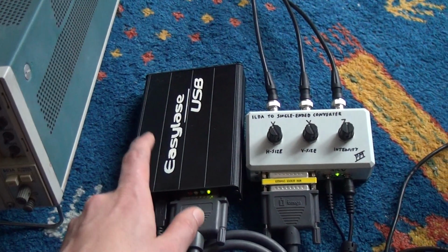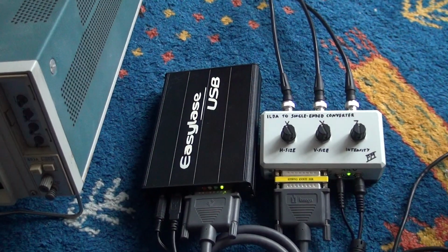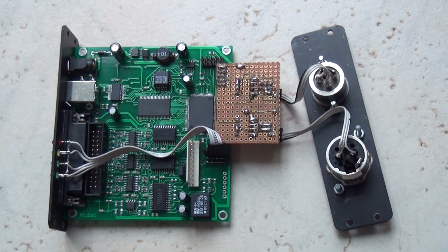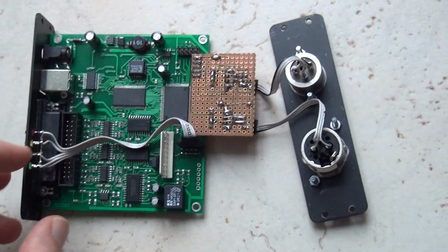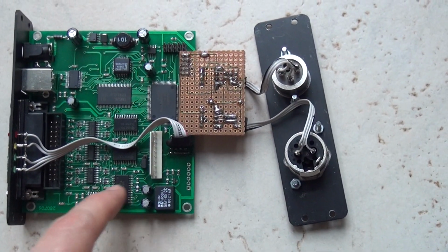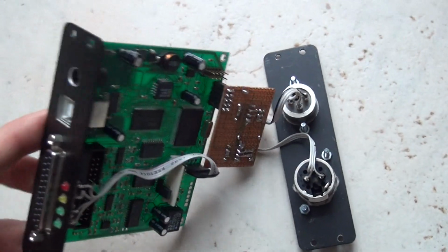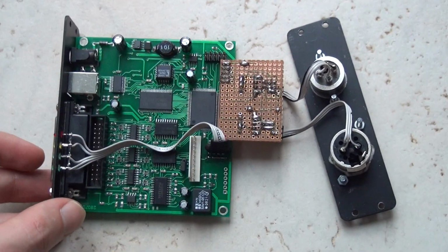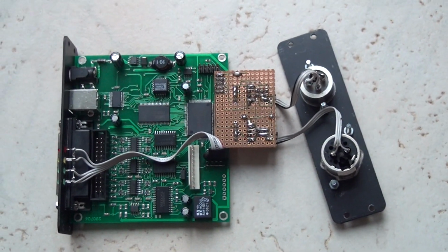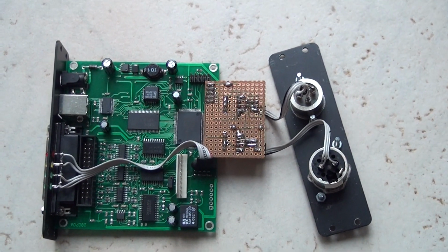And then I have the EasyLace USB, and I suggest we take a look at this one now. So this is the inside of the EasyLace USB I use here in my project. This is basically a little microcontroller PCB with some digital analog converter and operational amplifier that drives the ILDA port here. These EasyLace USB devices are very common in Germany. Many laserists are using them with different software. It's supported by LDS and HE laser scan, all this stuff.